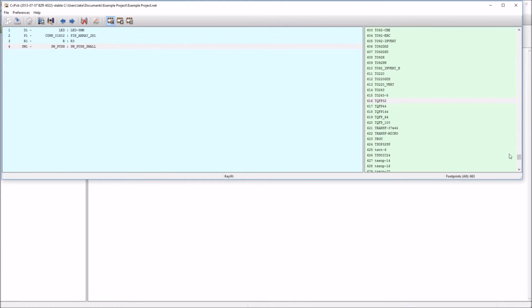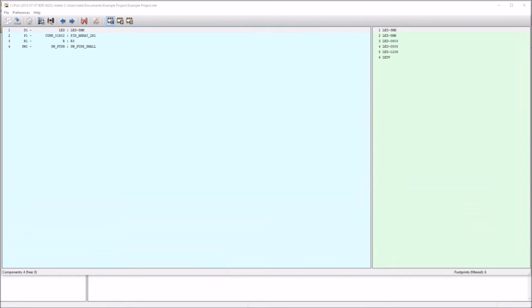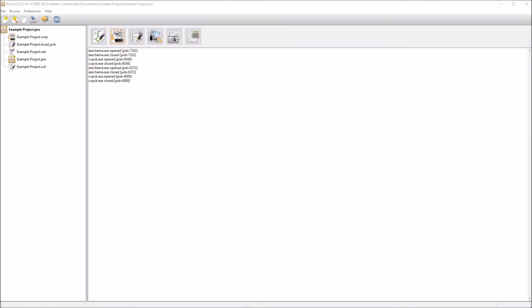And they have a lot of packages here. You can download more. Everything you can just add from the download libraries. KiCad has their own libraries you can download from, and you can download from any website that has suitable ones. Also, once you finish associating the parts with the footprints, you just go File, Save, and it saves it to the netlist, and that's pretty much all you need for that.